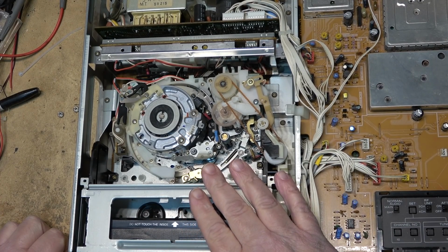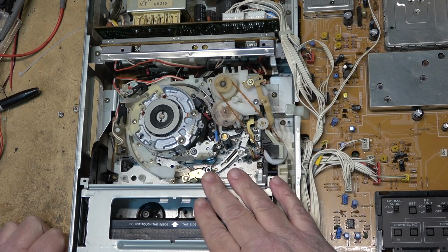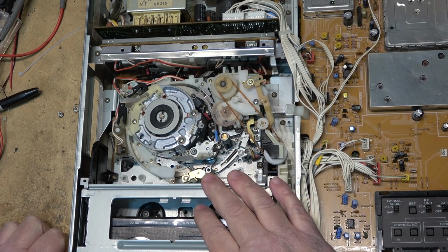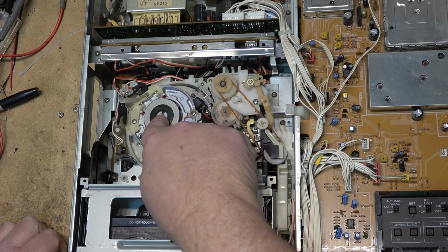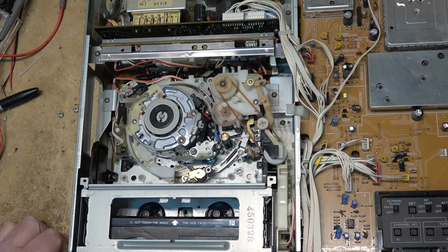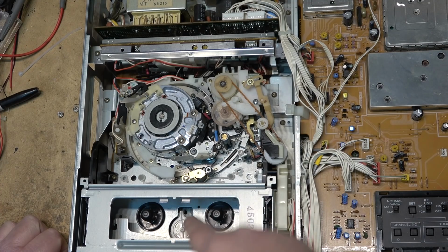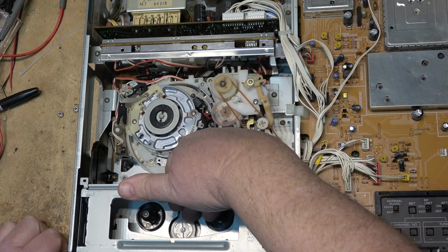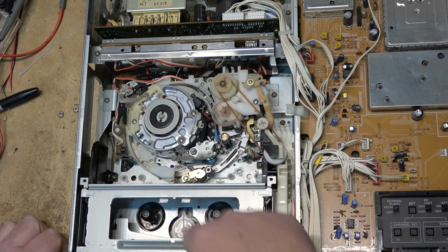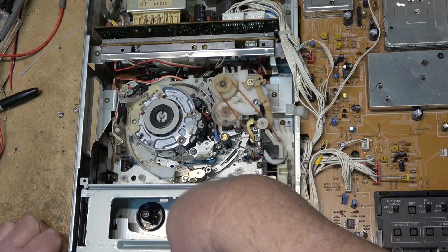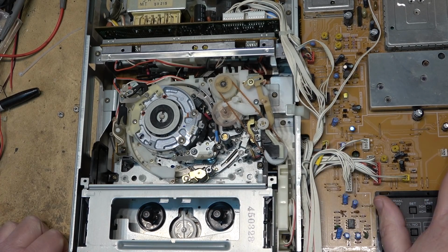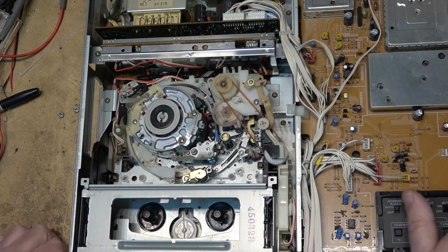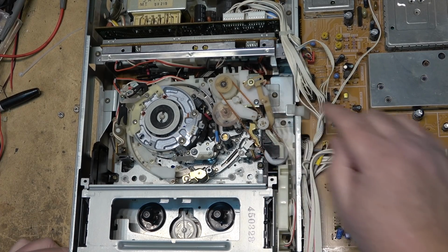So this is a 711 chassis, 711B chassis, I believe this one was called, and it uses a 4-motor system, sorry. 1 drum motor, a capstan motor. It has a reel motor down here with a pendulum gear for both fast forward and rewind and play. You can see the motor down below that gear. And it has a combination loading motor using a planetary gear set, and there's a solenoid. You'll see it here moving.